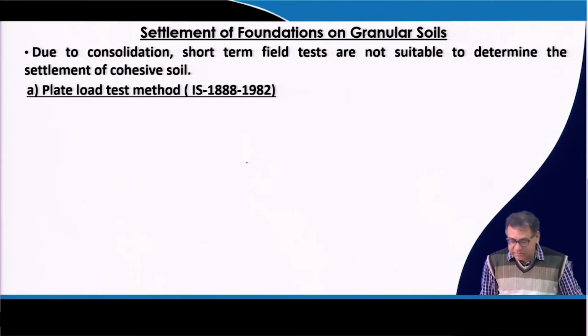The plate load test is done in the field. This is the field test for the shallow foundation, by which we get not only the settlement but also the bearing capacity of the foundation. The advantage of this test is that in most field tests, we determine the soil parameters directly or indirectly, then use those parameters in our bearing capacity equation to get the bearing capacity.